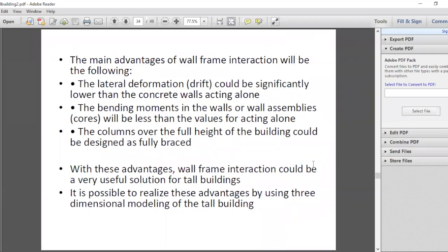The problem is, if the frame starts moving laterally, there's nobody to bring it back, right? No strong elements to bring it back. So that's why, in an unbraced frame, we design the columns to be very strong so that it will never move without any control. Is that clear? Yes, sir.